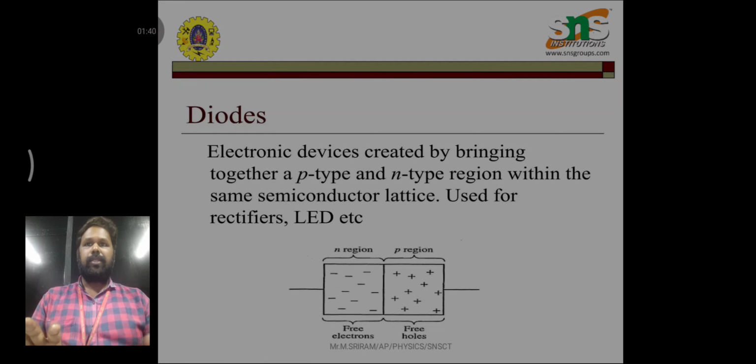And diode construction. Diodes can be made of either of two semiconductor materials, silicon and germanium. When the anode voltage is more positive than the cathode voltage, the diode is said to be forward biased, and it conducts readily with a relatively low voltage drop.